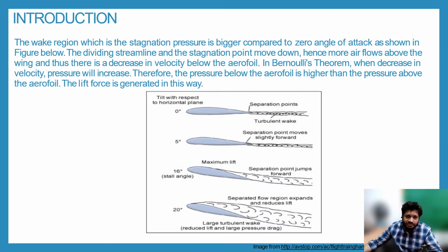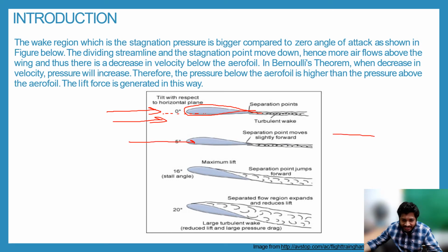So you might have gone through this theory in Fluid Mechanics 3 as well, that you've got an aerofoil and you've got an upstream velocity fluid which is coming. Now the angle that it makes with the upstream velocity is very important, and that angle basically decides what is going to happen at the back end of the aerofoil. So in this region, as you change the angle of attack from the upstream velocity, the separation occurs, the flow separates from the body.